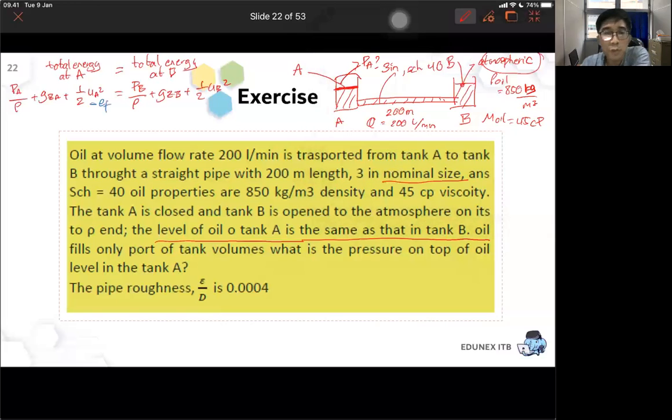Then what do you need to do to calculate EF? How to calculate EF? You need to first quantify the value of friction energy in the unit of specific energy. That's why all the energies, whether it's pressure, potential, kinetic, and also the friction, will all be in the unit of specific energy, joules per kilogram. How to calculate EF? Or where does the EF come from in the system?